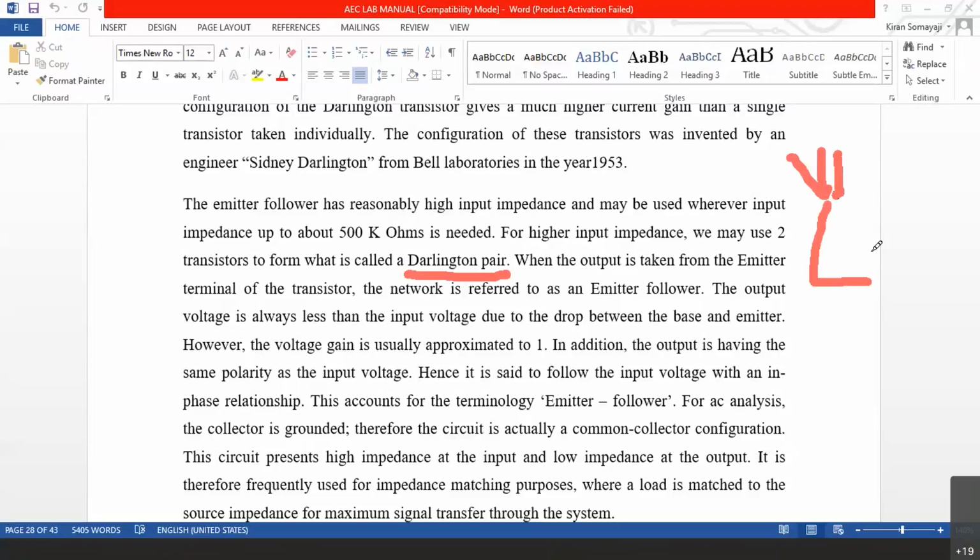From the antenna, initially you should have a preamplifier. This preamplifier is going to pick up the RF signal from the outside and gradually amplify it. Now, when the input signal is in picowatts, naturally we require a very high input impedance for this amplifier. Because when the input signal is very weak, when we use a preamplifier, the amplifier should not drain the energy of the input signal itself. That is why we need a very high input impedance.